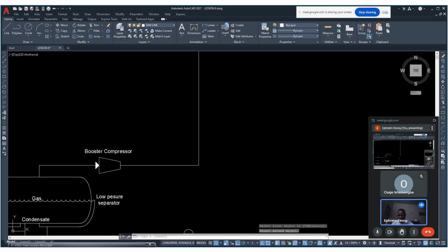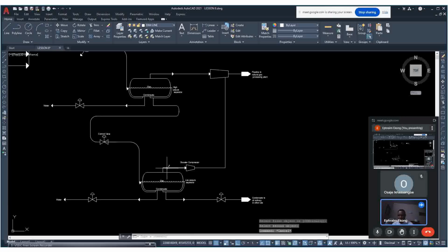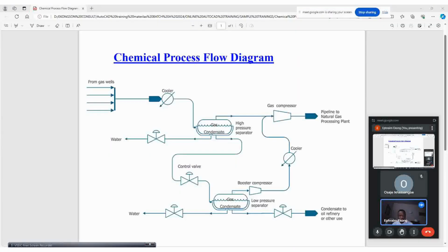What do we do? It must work. Click on fillets, type R, enter, 400, enter. Click at this line. Do it again. It's taking time, honestly. It's not working. What do we do now? I think the best thing to do is to copy.